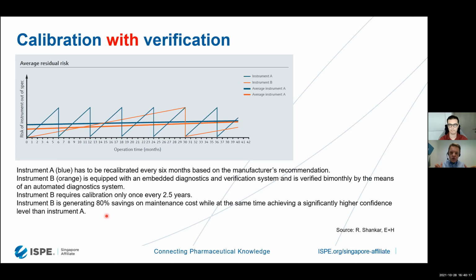while you usually have a fixed calibration interval for your critical instrumentation, this can be, first of all, periodically reviewed. Second, it can be based not only on the existing standards and manufacturer's recommendations, but on your master data coming from that instrument that will affect your calibration interval. So it can be individualized and it can be made more dynamic.